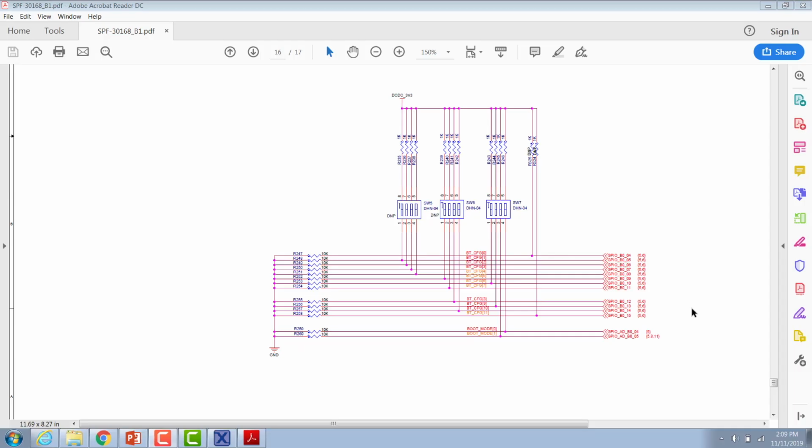This is the boot mode and boot configuration selection circuit used on the 1050 EVK. You can see here we have switches that allow you to select a number of options for the boot mode pins here, and then there are also 12 different boot configuration pins. The boot configuration pins are used to configure your boot device so that the ROM has enough information in order to perform basic access to the memory, which can then be reconfigured later.